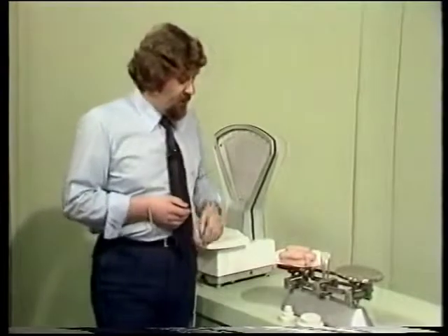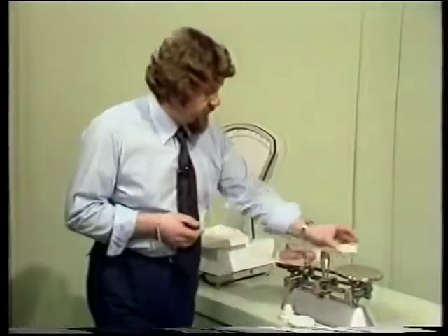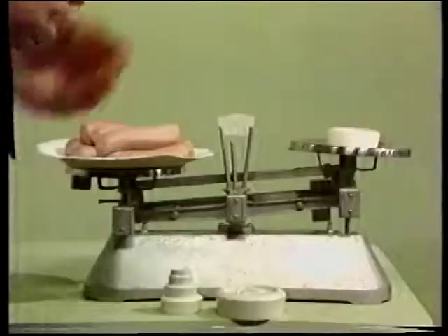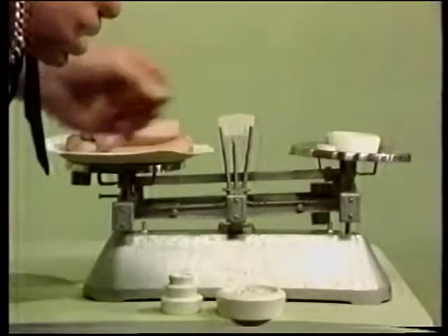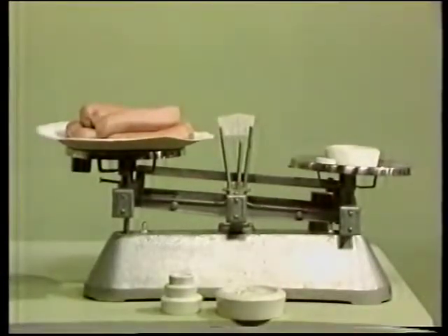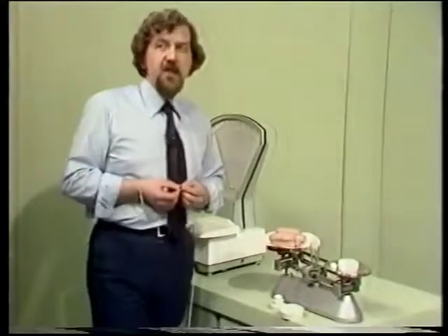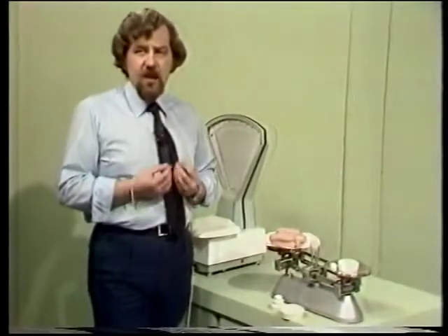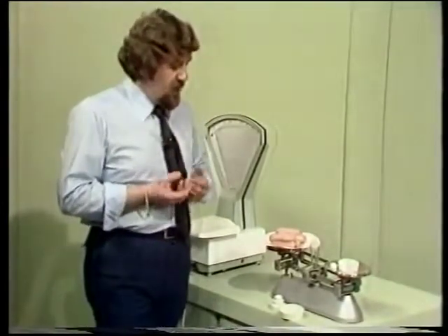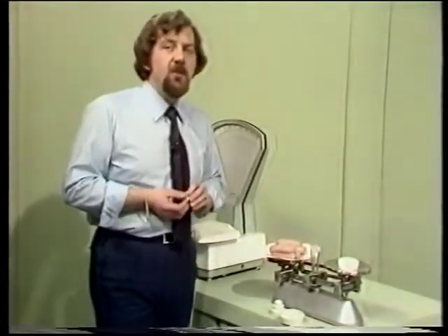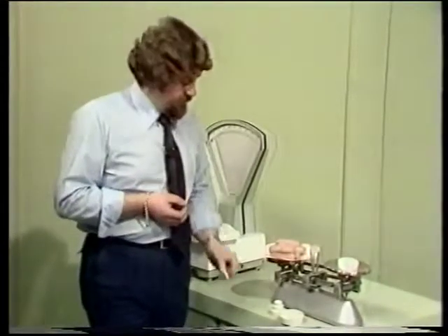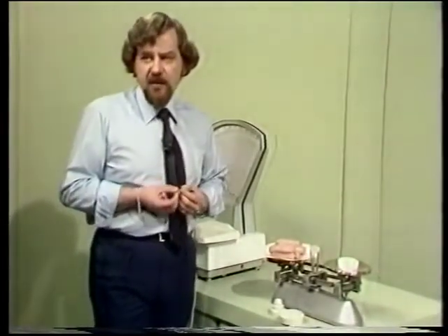So let's put some weights on. They're about a pound, so I'll start with that. Well, that's not quite enough, and 17 ounces is just too much. So the actual weight must lie somewhere in between. I can't get a better measurement because the smallest incremental change I can make is my 1 ounce, and it's called the quantization interval. It determines the measurement resolution. In terms of the A to D converter, it corresponds to the voltage represented by the least significant bit.